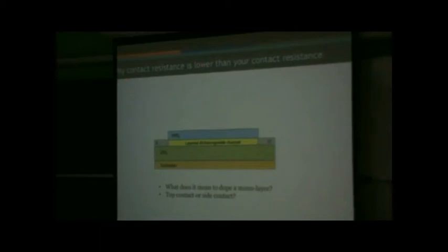So the third thing is contact resistance. I intentionally say my contact resistance is lower than your contact resistance, because if some of you were at the recent IBM meeting, you know that there has been some very entertaining and engaging discussion about this. But what we are really fighting, when we do experiments, is: I put metal X, you put metal Y, I get this much current, you get that much current. The problem is, this is not very relevant in my opinion, because even if you have a very good contact metal, the VT changes when you change the voltage. And so that's not a good transistor.